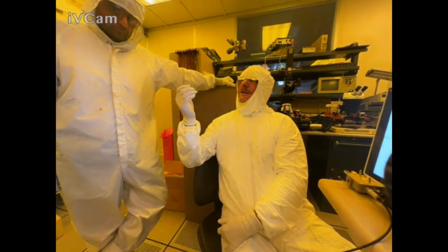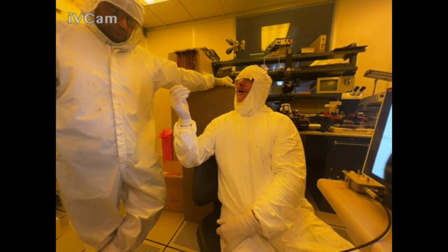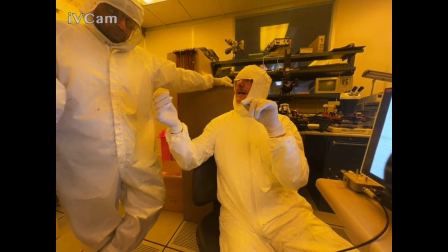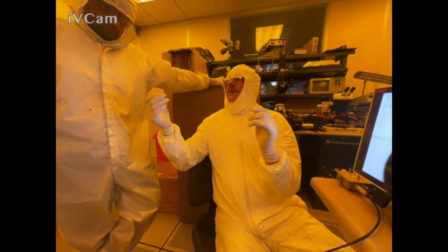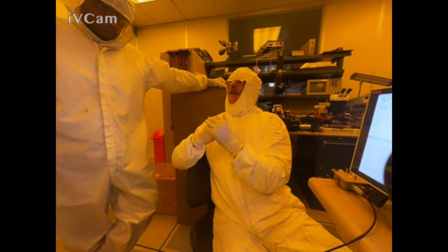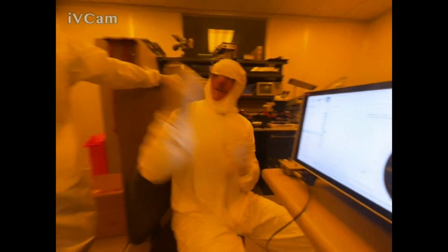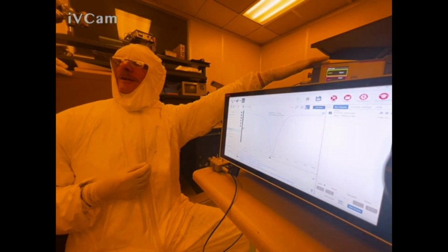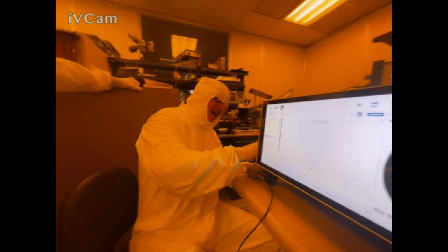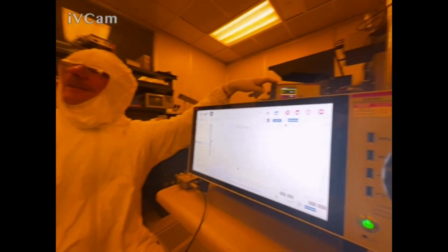They're shorted. I don't care about those leads anyway. All I care about is the gate and the bulk, basically, and the bulk is tied to the drain and the source. So I've shorted out those parasitic capacitors. Now, that's one way to do it. If you don't have this, it's the only way to do it. With this, I don't have to worry about that because I can short those pins with this.